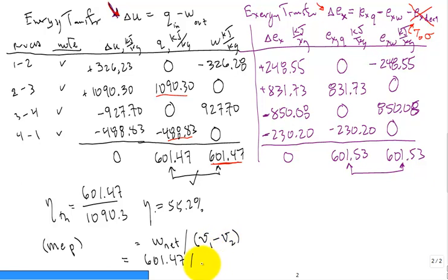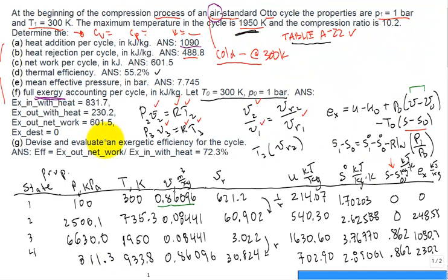And did I make that calculation? Let me take a look if I did. Yeah, it's 0.77655 meter cubed per kilogram. Okay, and then the units, when you run it, the mean effective pressure comes right in at 774.5 kilopascal. They want it in bar, move it over by 2, so it's 7.745 bar. Go back and check. Did we get that right? Yeah, there we go.